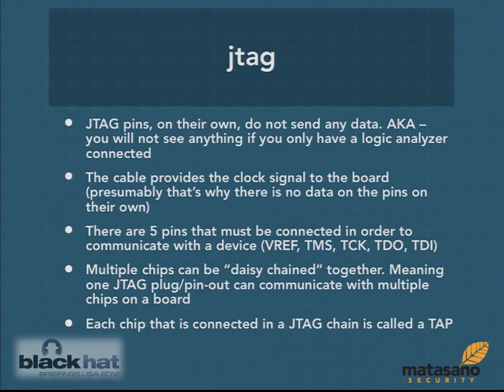First is that I wasn't seeing any data because JTAG pins on their own don't transmit any data. The clock is actually outside of the JTAG ports, and that's what determines if pins should be transmitting or receiving data. So you need a specific external cable. You can't just plug in the logic analyzer, because something else needs to be triggering this clock up and down.